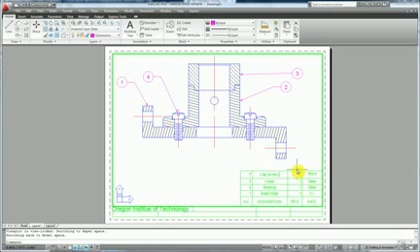Notice how all the parts, except for the cap screws, were drawn with section views. This shows the inside of the part where most of the detail is, to show the assembly, as far as how far the screws go through the part and how much the collar goes into the bearing. Also notice all the cross hatch lines are at different angles. This helps distinguish one component from the next.